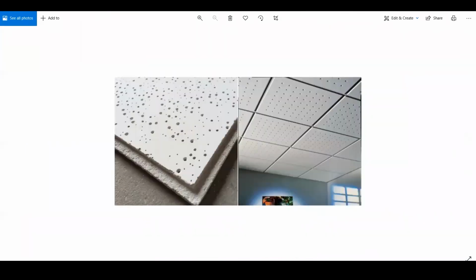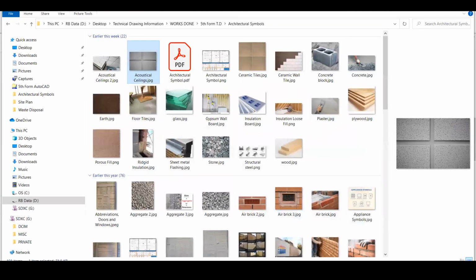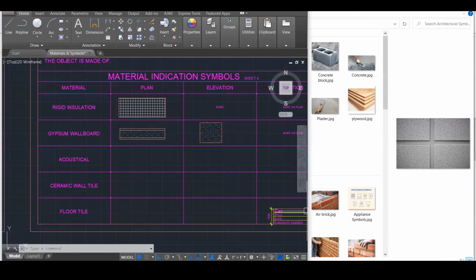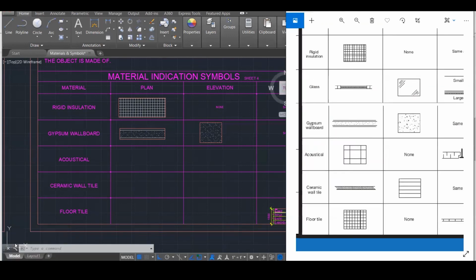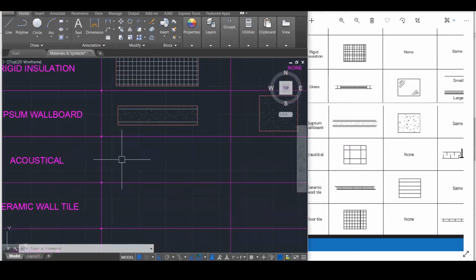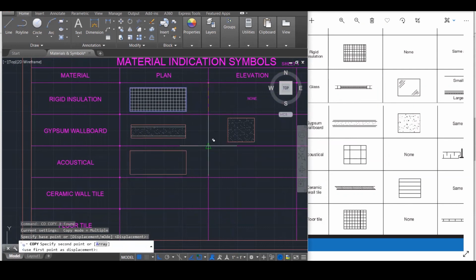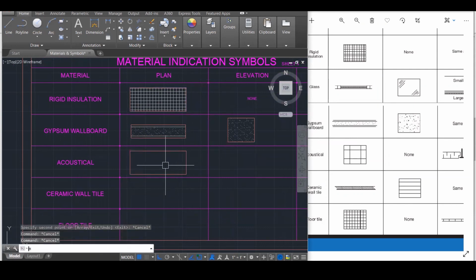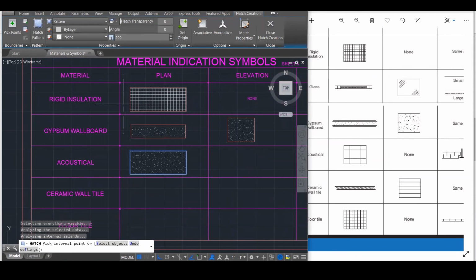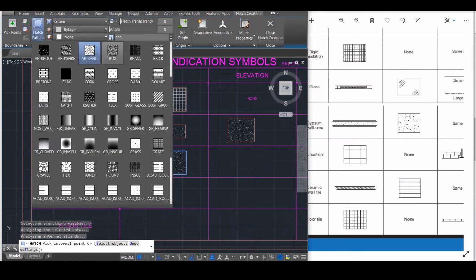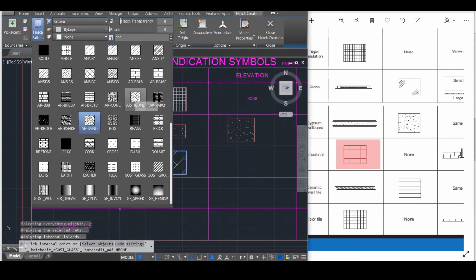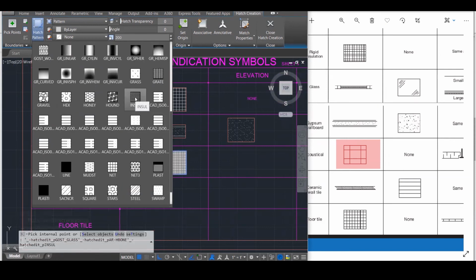Let's go back now to placing this in. How do we represent this in AutoCAD or in a drawing? Well, first thing, you need a rectangle. So I'm going to bring this down. Copy this rectangle, CO for copy. Bring down the rectangle, H for hatch, bring up the hatch menu, and search for a pattern. I'm looking for some big squares, big rectangles.